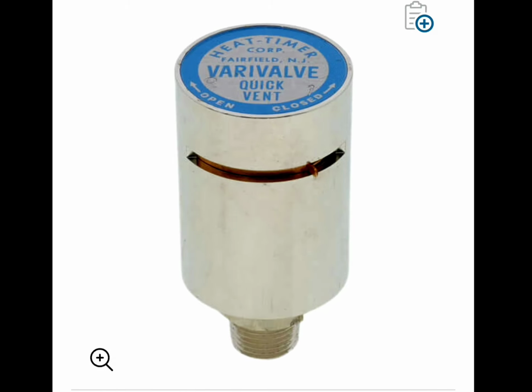And this is a relatively small air vent. And although it looks impressive, however, I'm going to tell you this is not the vent that you should be using on radiators. As a matter of fact, I'm kind of skeptical about these vents, period. I mean, you can put them on radiators, but I really don't recommend them like that. There's two reasons why I don't really recommend these particular air vents. You can use them on steam risers. However, I'm not too certain whether I would put this on a steam main.